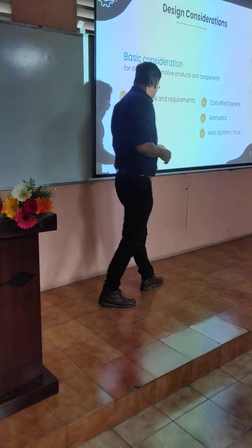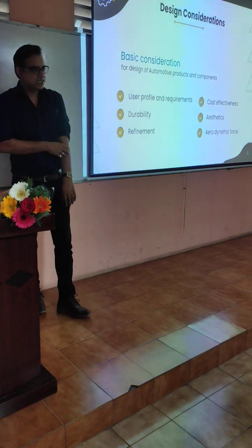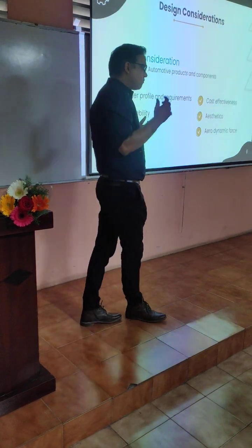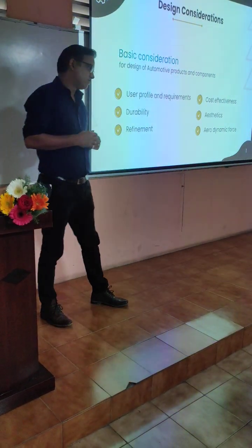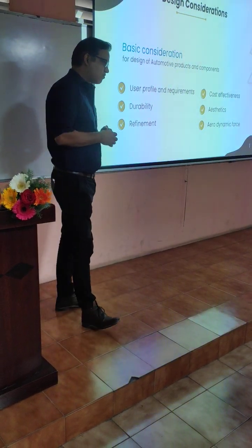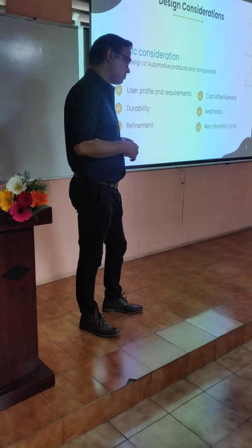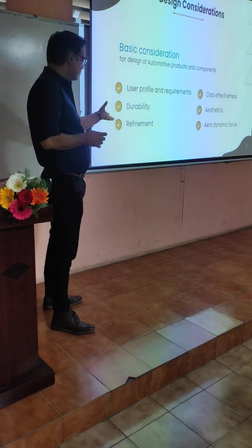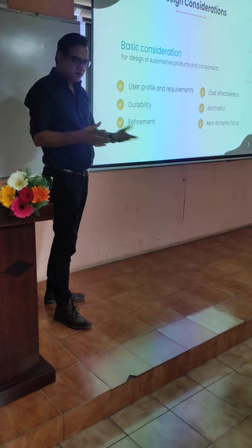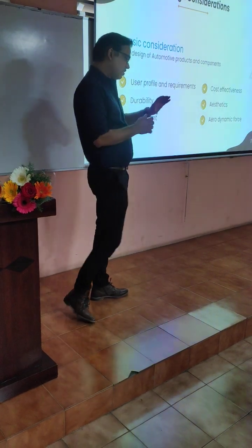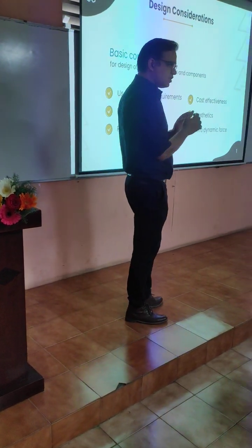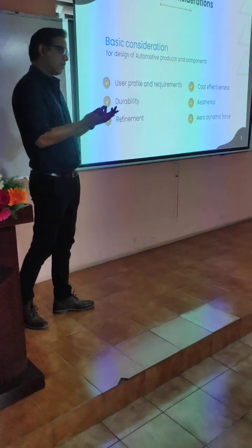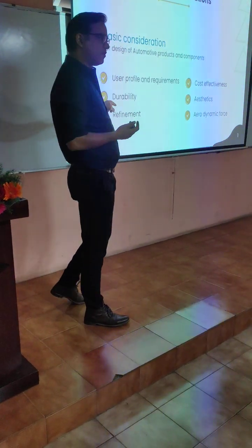You have to go for refinement. In automotive, refinement is everything. You buy a vehicle, it's vibrating, you get a whining noise, you get a rattle when you go through a bad patch of the road, you get a clanking noise. Product is dead. You don't want it. If you are automotive engineers, you must have seen open vehicles sometime. You will see all the panels have a rubber boot below. Even though it's screwed hard to the chassis, still there's a rubber. Why? It's for that refinement.